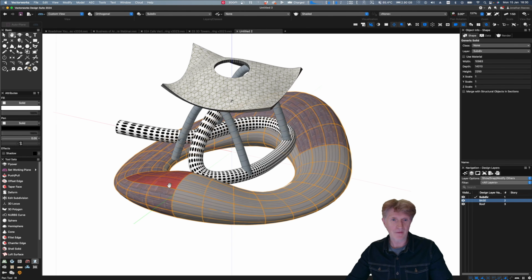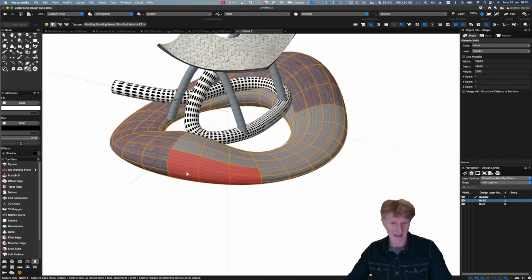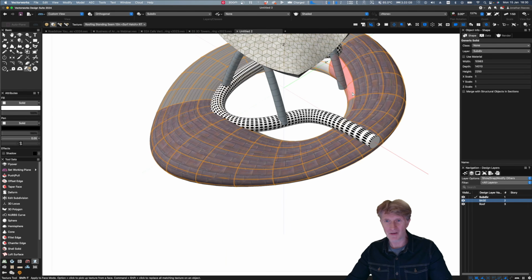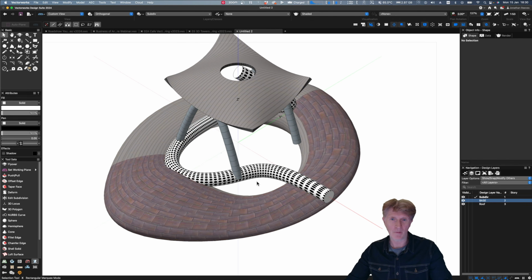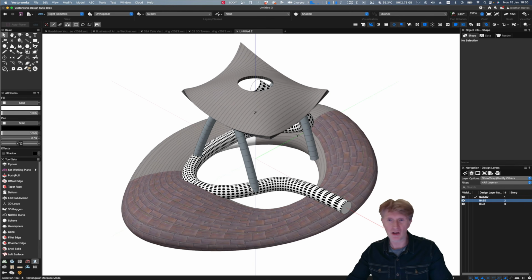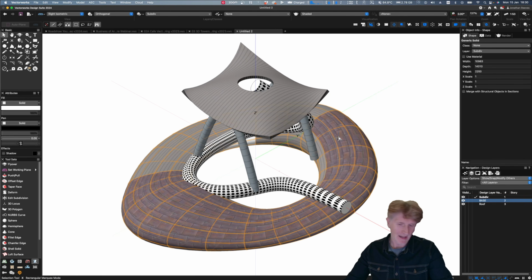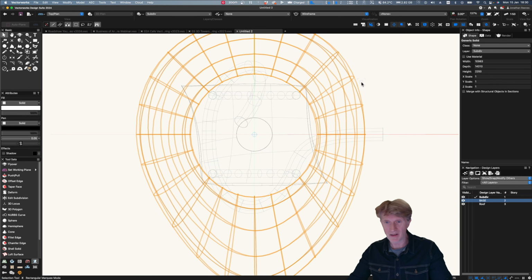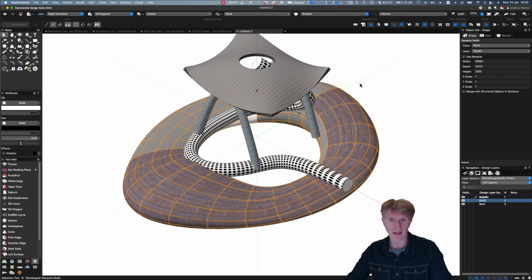So I really, really love the flexibility of freeform modeling. As I say, sometimes it's actually good fun not to model anything specific, but just to have a little play with the Vectorworks sort of freeform modeling. And the purpose of the video really was to show you the 3D dragger. Now obviously I can't click onto the reshape tool now and go back to my solid because this has got no history. But what I can do, if I do want to, is do things like split it.